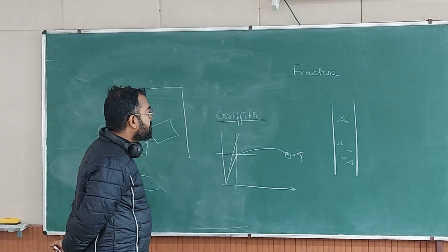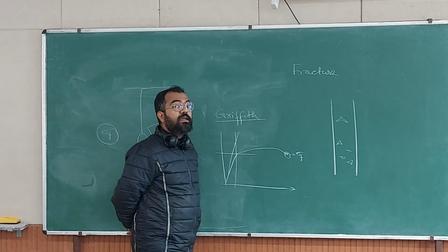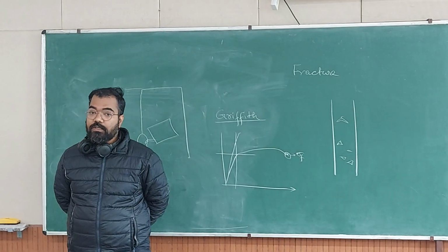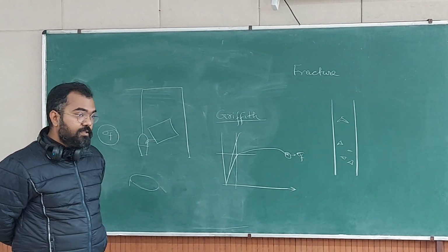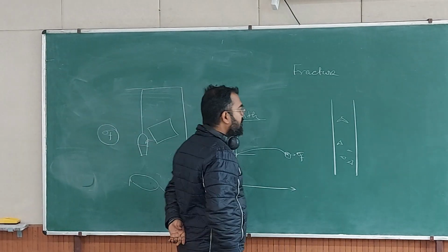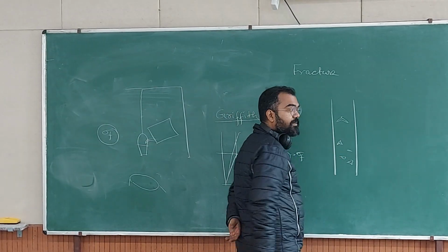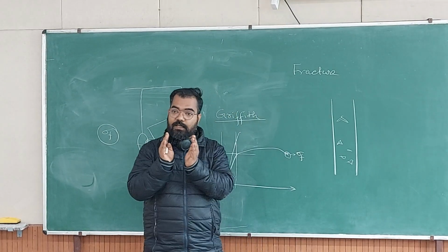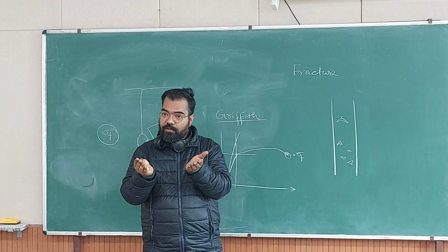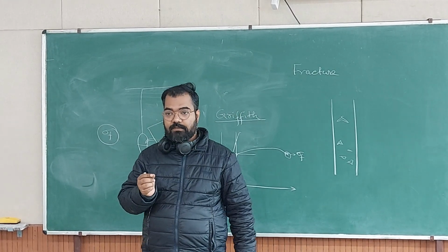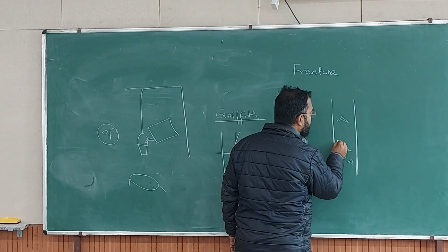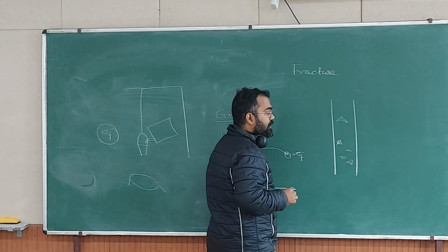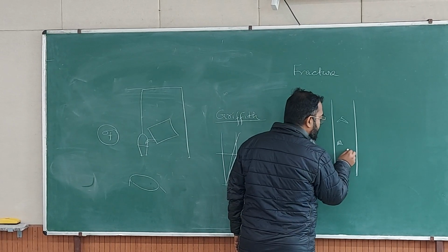The fracture stress for graphite, carbide or oxide inclusions is also very small, so most of them are going to break. Now there is a surface with no load on it. If it is ductile, this will act as a void. If it is brittle, it will act as a micro crack.